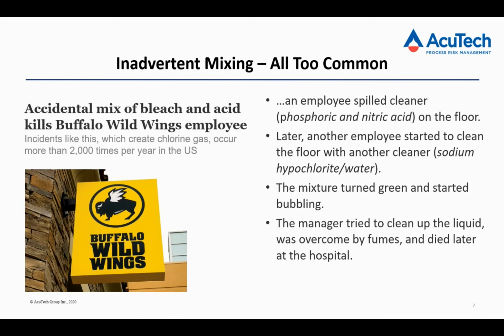This first event was at a Buffalo Wild Wings restaurant. An employee released chlorine gas. He was mixing a cleaner that contained phosphoric and nitric acid with another cleaner that contained sodium hypochlorite, or bleach. A manager trying to clean up the mess was overcome by the fumes and actually died at hospital.